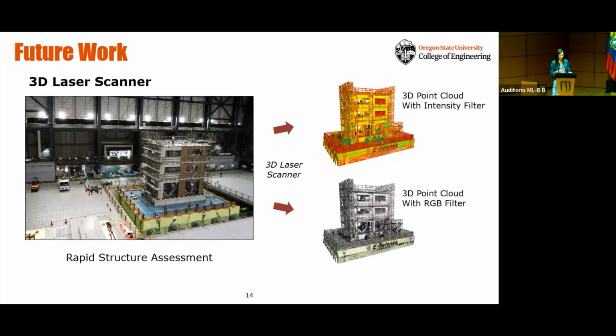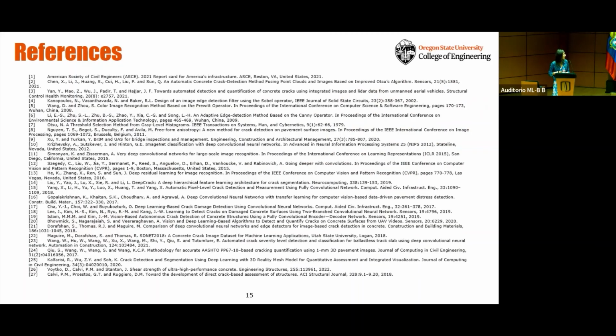So my colleague Paolo actually collected a whole bunch of 3D point clouds from that building, and they're trying to manually extract the cracks from the laser scan. So we're also going to look into whether we can use this approach on the LiDAR point cloud. That's going to be our next step after the image recognition.